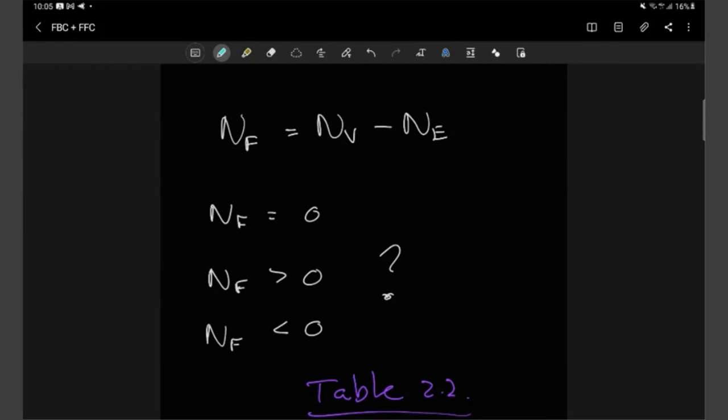If it's greater than 0, obviously we have to specify something else because we have open degrees of freedom, which makes our system solvable by an infinite number of solutions. And then NF smaller than 0, you did something wrong, it's overspecified. You need to reduce some of the specifications that you introduced, or there might be some incorrect equation or variable specification.